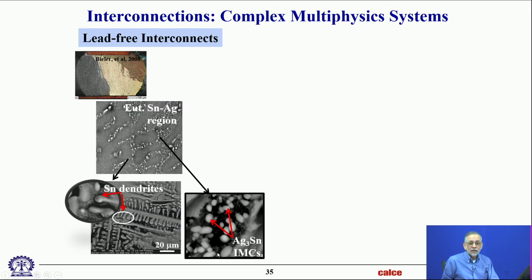Okay, number one. Number two, Professor Ramanujam was very intuitive. He also talked about, what about the stress strain curves? These creep a lot. Like plastics, these are highly viscoplastic materials. What does that mean? It means its melt temperature is very low. Plastics have low melt temperatures compared to metals. Solders are special kinds of metals. They have very low melt temperature. Why? Because we need to be able to solder it without damaging the electronics. So we choose metals with low melt temperature. The downside is, now even at operating temperatures, I'm very close to a melt temperature.